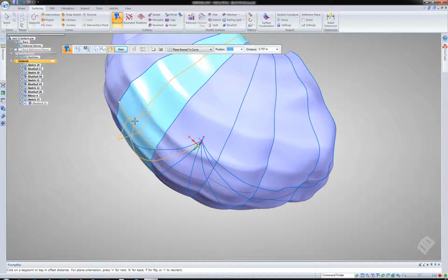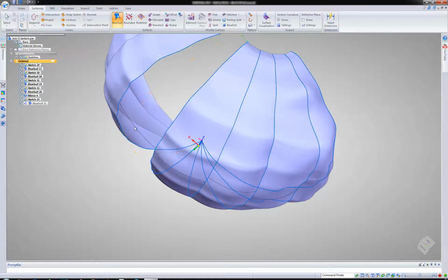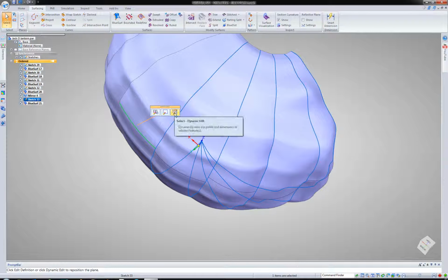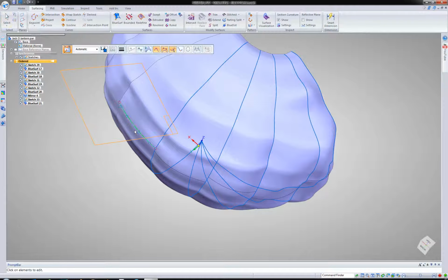And as you can see, I clicked it again. We can add more guide curves. So I can actually curve it in multiple directions, or again I can curve it, add multiple guide curve faces down the body here. I'm just going to go ahead and do the one. Go ahead and modify that guide sketch, or the inserted sketch.